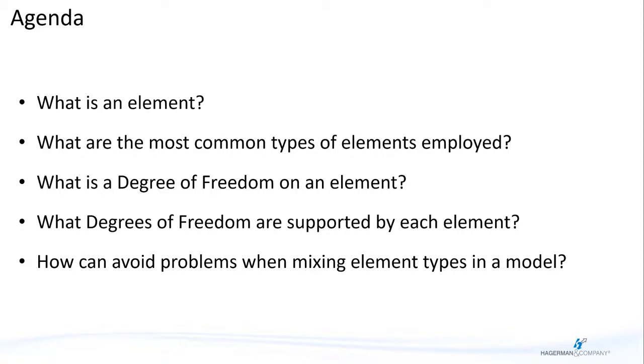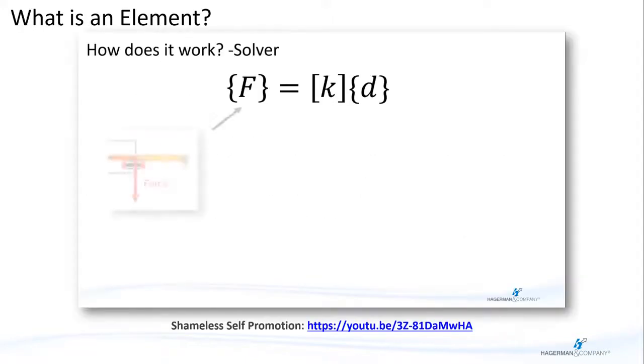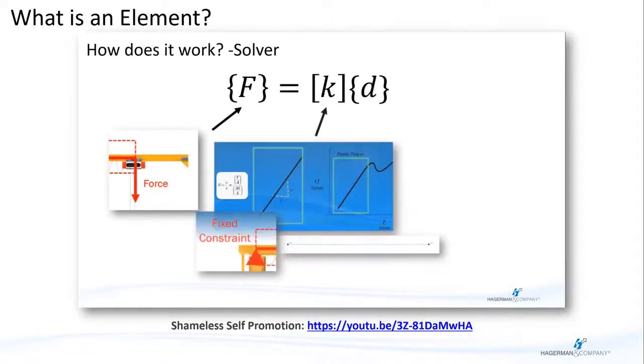Although I'll be using Nastran and CAD, this concept is something that anyone using any FEA program should get a grasp of. I suspect it's little known and little understood by designers and engineers who aren't expert analysts, but only employ this technology part-time. Anyone who's been in any of my training classes may have seen me struggle to explain these concepts on the fly, as training materials rarely discuss degrees of freedom. I remember learning this stuff myself, and topics like this were often described by help documentation in ways that were less than helpful. We can't talk about degrees of freedom without talking about the element.